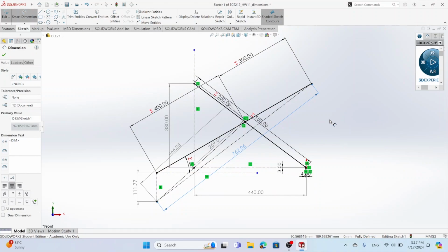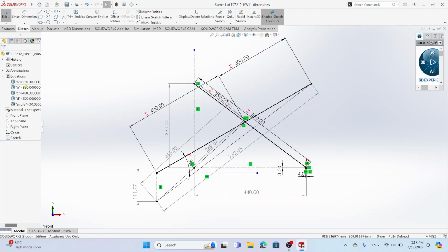Okay, I know there's a lot of dimensions. You can remove them when you build your sketch, but it took us, I don't know, 5-10 minutes, and we can check all the dimensions that we found by hand with the sine law, cosine law, and all of that. There are so many options to make mistakes because all those triangles inside don't have right angles. So I feel like it's an easy way to check your dimensions. And don't forget to save, close, and let's say you take a new attempt.